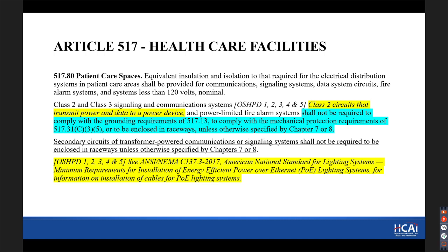Next question. So the GFCI receptacle in elevator pits would need to be accessed every month to test? That's a good question. And same for the sump pump. So yes.